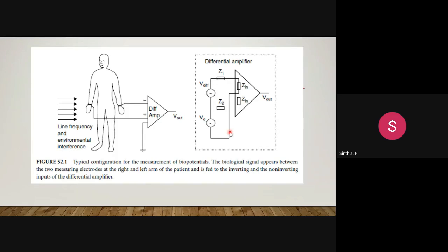In order to provide optimum signal quality and adequate voltage level for further processing, the amplifier has to provide a gain. Next, coming to gain: 100 to 50,000. It has to maintain the best possible signal to noise ratio. The presence of high interference signals will deteriorate, or lower, the quality of the physiological signal. In addition, it will also restrict the design of the bioamplifier.